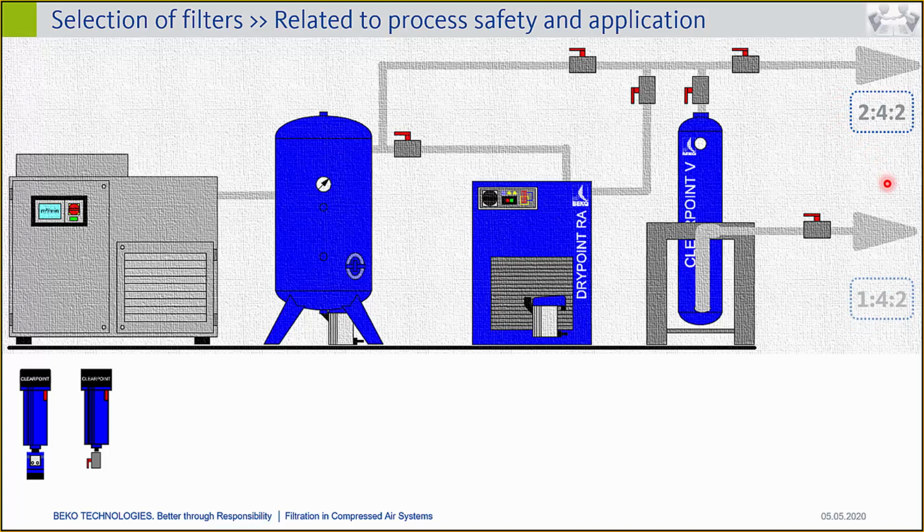The oil-free application for sure requires a higher quality with fewer particles. But we would not be able to achieve class 1 here, not in the given situation with the integrated fridge dryer in that combination.